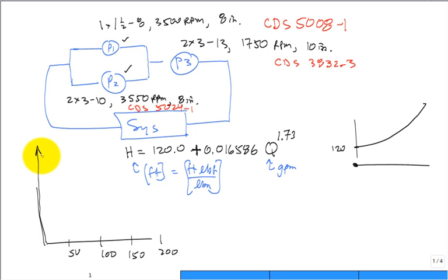We're going to use the 8-inch impeller. Highlight that line. Isn't that the topmost curve in this sequence of curves for pump 1? Highlight it so that we know that's the one we're working with. That's our actual pump 1. Now let's go to pump 2 and ask which impeller we used. We didn't put in the biggest impeller, the 10-inch, it's the 8-inch. So highlight that line.